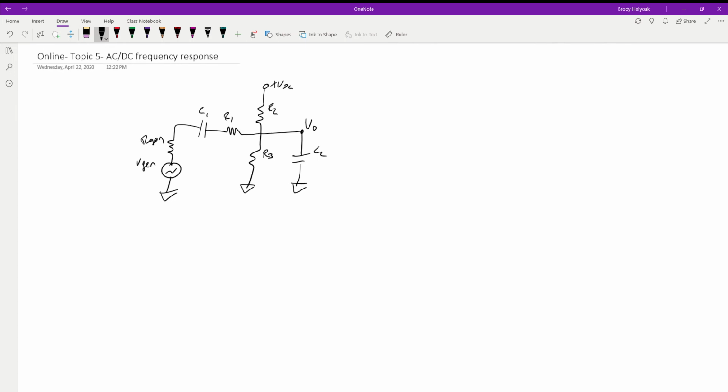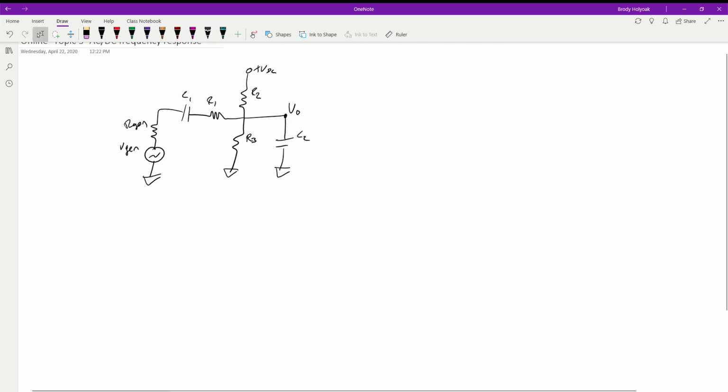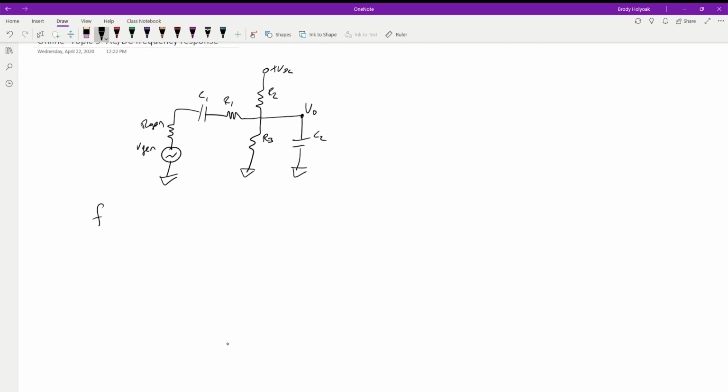One of the things we want to look at, when we're looking at these critical frequencies, is some rules of thumb. We're going to find FC1 and FC2 based on this circuit, and these are going to come from capacitor 1 and capacitor 2. What we have here is a couple of ideas and rules that we've learned before, just to see them in an actual application. At our critical frequency 1, our X of C for capacitor 1 is, and I put this in quotes, normal. It's not obscenely high, it's not obscenely small, it's where it should be.